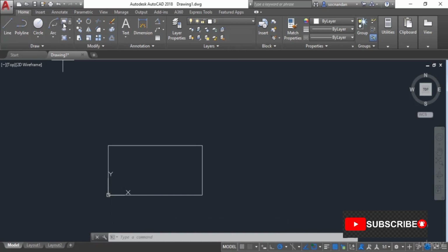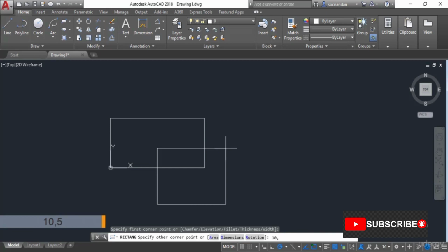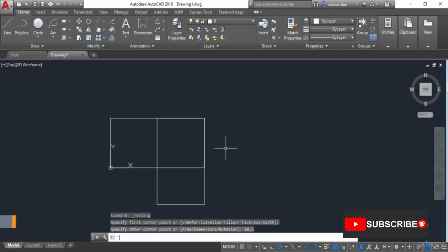But what if we make the same rectangle not from the origin? So I'll start the rectangle and click anywhere in the drawing area to make the rectangle, and that will be the first point. Now we again need to make another rectangle with length of 10 and width of 5 units, but in this case I'll simply enter 10, 5. And now look at the results. And instead of making a rectangle with length 10 and width 5, the next rectangle simply snapped to the same point, which was 10, 5.